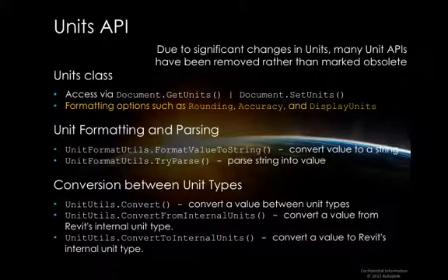The Revit 2014 API provides a predicate to test whether a symbol is active and a method to actually activate it. Units in Revit have always been a source for confusion. We cleaned up the whole unit handling, implemented a new streamlined units API, and initially planned to retain the old API in parallel to the new one, but finally decided that that would be rather confusing. So the old API has been removed, and that means that applications that make use of some unit methods will need to convert to the new API.